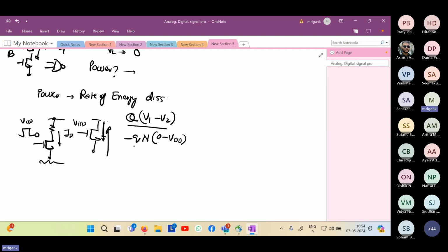That means the electrons are losing energy. They are going from a lower level to a higher potential level. So when a negatively charged electron goes from lower potential to higher potential, it is losing energy, right? So the charge transfer is the major reason for energy dissipation. The energy that is getting dissipated is because of the electrons getting transferred from a lower potential to a higher electrostatic potential. How much is that charge? The total amount of energy dissipation is the total magnitude of charge times the voltage across which that charge is transferred. That is the fundamental thing.